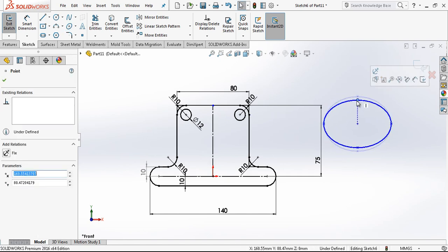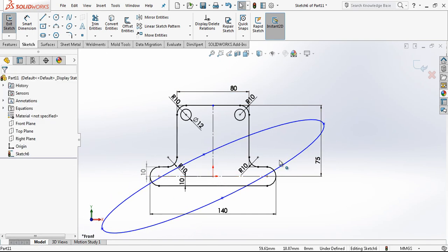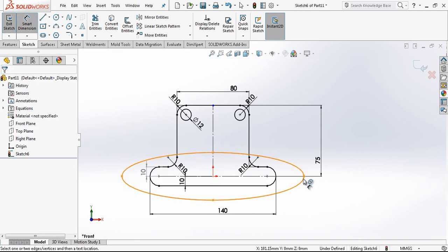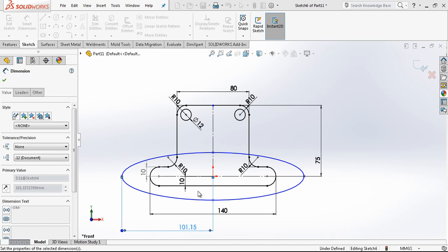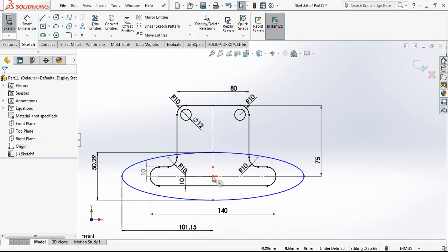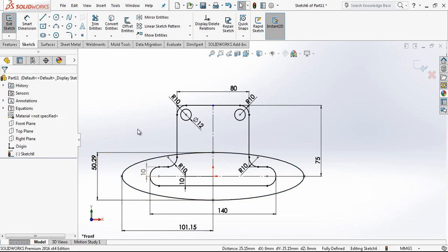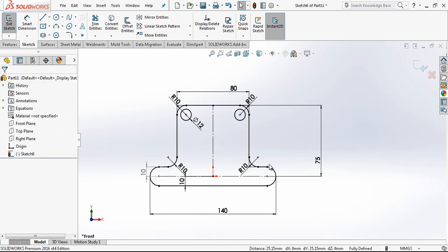For defining one ellipse, for example, if you are going to bring it in the origin, it is not only enough to give the dimensions, the program is also going to ask you, for example, the directions of the points. When you make it vertical, it's simply fully defined. These are little tricks. By the time you make examples, you are going to have it.